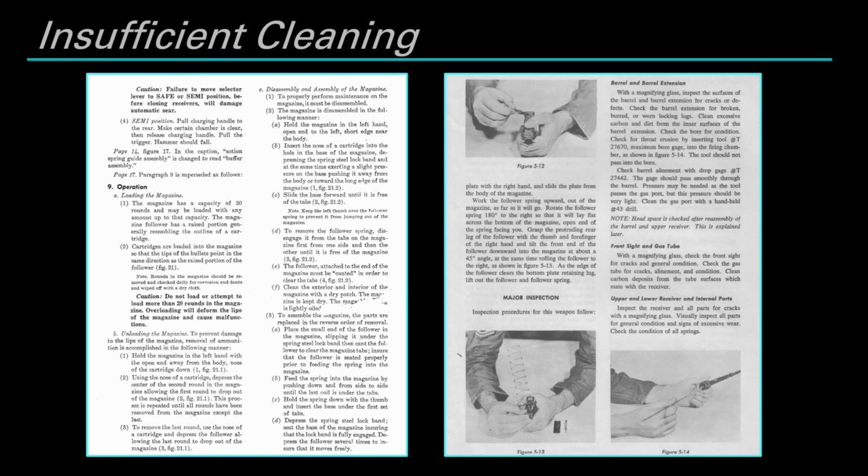However, pretty much across the board, whenever Colt and the Army had their independent inspectors go to Vietnam to try and investigate issues, one thing that they found very frequently was that magazines were not being properly maintained. They would find magazines packed full of grease, and the justification for this was that it would lubricate the ammo, and then with the ammo being lubricated, the rifle must run more reliably. In reality, the magazine packed full of grease just let sand and dust and debris accumulate in the magazine, get coated onto the ammunition, and then delivered into the chamber of the rifle to build up to the point that the rifle would then jam and become inoperable.